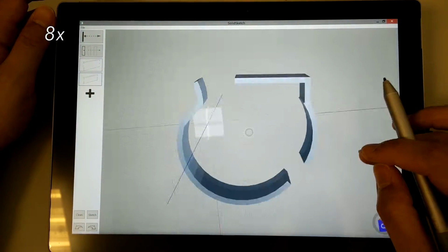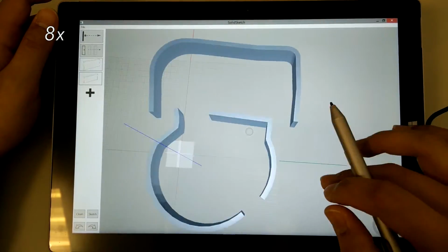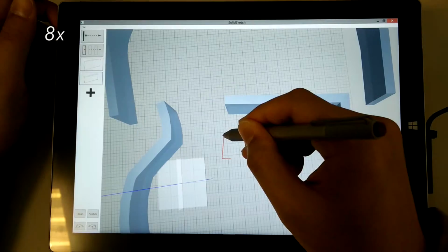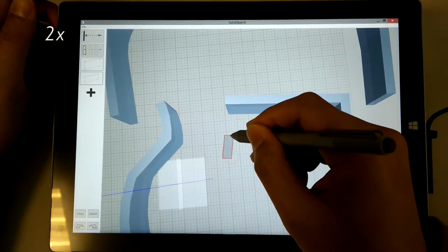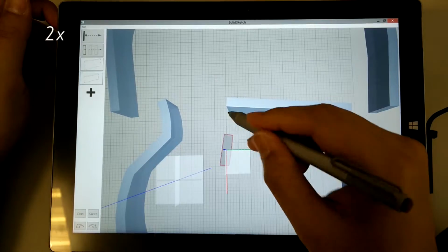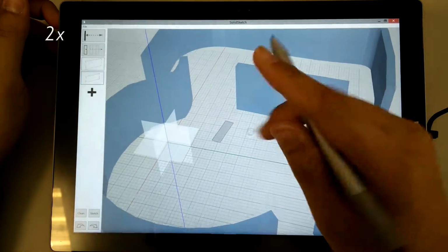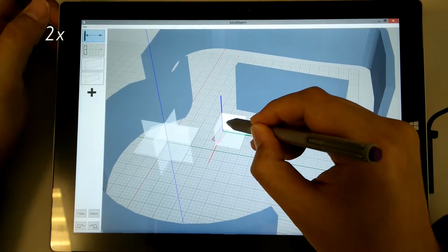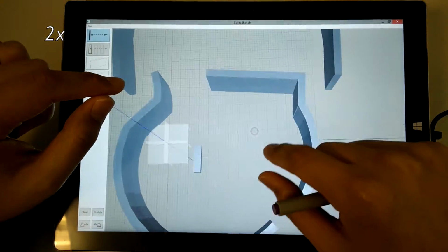Here, we describe the interaction designs of Solid Sketch that enable an architect to explore their ideas in the early stages of design. The user can create an accurate rectangle by performing right-angle gestures at the corner of the shape. The user can also oversketch on the selected polygon to modify the shape. In this case, we're trying to create a staircase, and use the Array tool to create the entire shape.